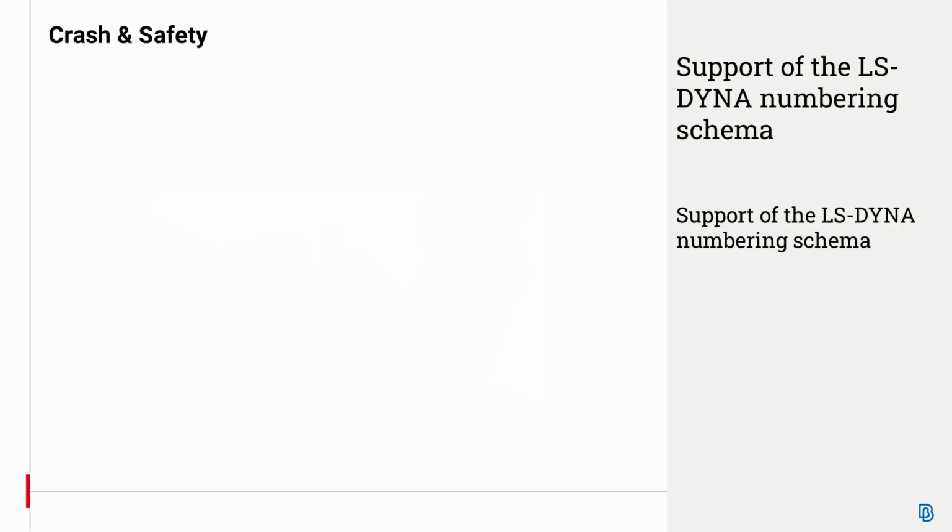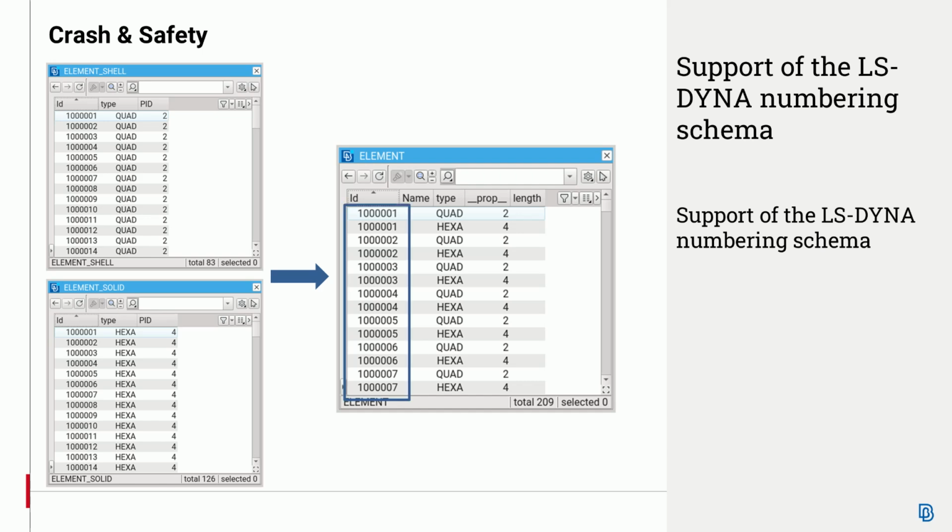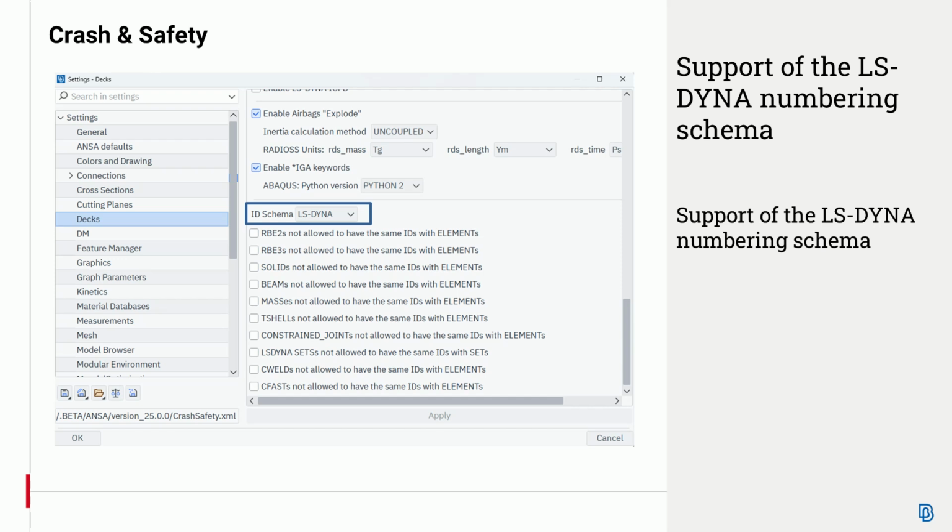Moving to the enhancements, the LS-DYNA numbering schema is now fully supported. This allows sharing IDs between different types of entities, such as shells and solids, eliminating the need for renumbering processes. This option can be enabled in the Settings window.